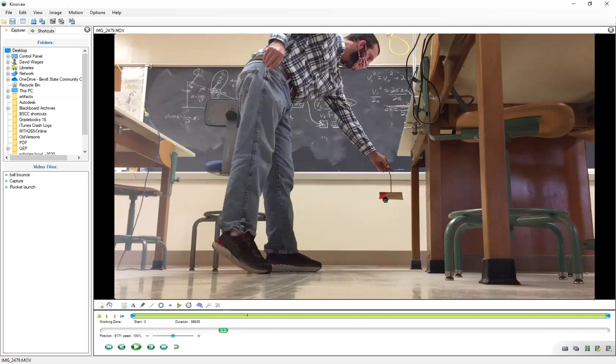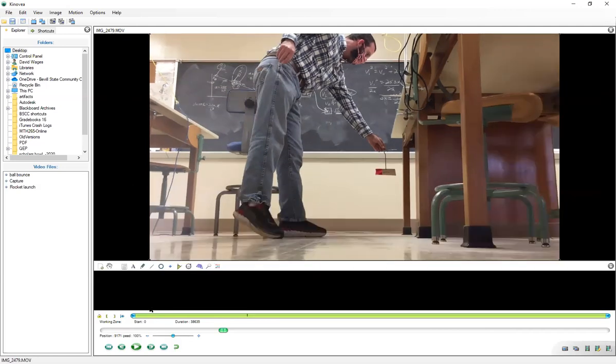You might have seen on the coordinates that had PX, it was just measuring basically how many pixels we had gone over or up. The software by default doesn't know what the distances are in this image. It doesn't know if this is something that's really, really tiny, or something that's really, really large. Are we in feet, miles, meters, what? So to calibrate it, we're going to draw a line.